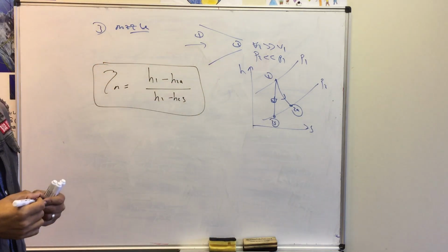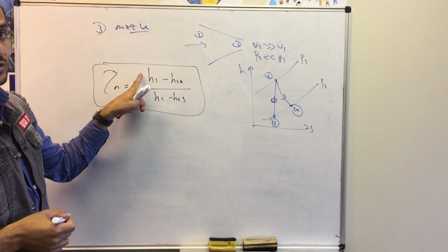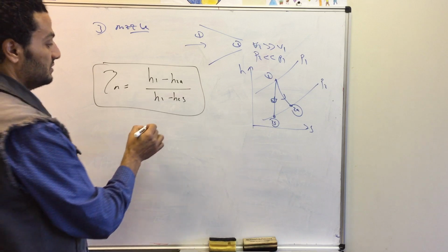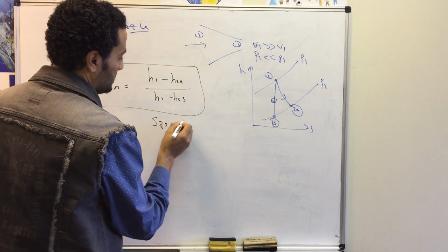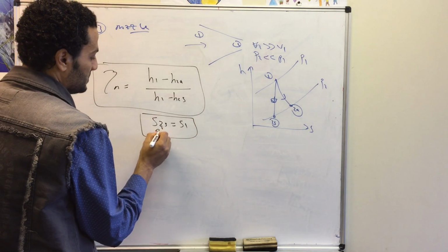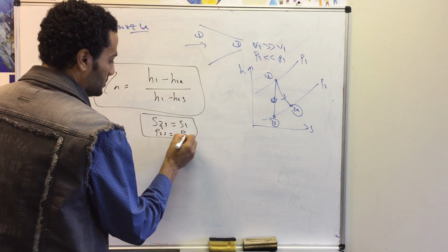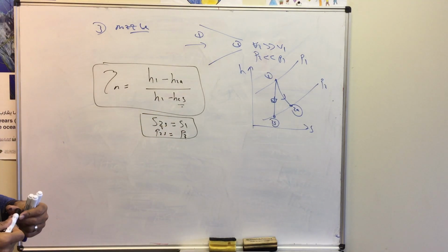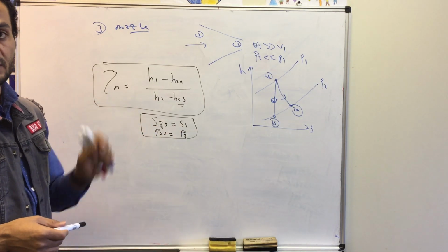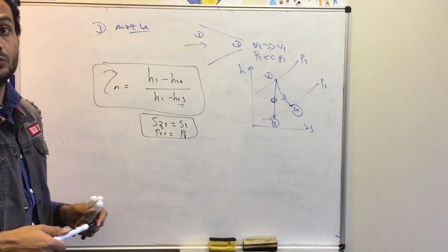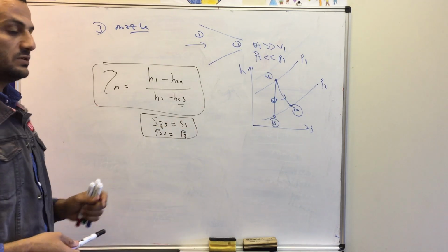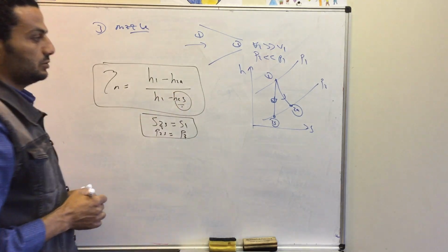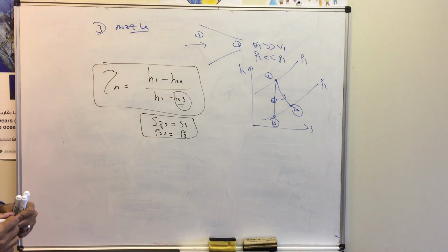If the flow through the nozzle is steam, we can get P1, T1 at condition 1, then we can calculate H1. At the exit condition, we can calculate H2, and S2s is the same as S1, and P2s is the same as P2, which should be given. Then we can calculate the value of H2s. If the flow through the nozzle is air, then point 1 and point 2s are isentropic, so we have an ideal gas undergoing an isentropic process. So we have to follow either the constant specific heat analysis or the variable specific heat analysis in order to calculate H2s. Then we can calculate the isentropic efficiency of the nozzle.